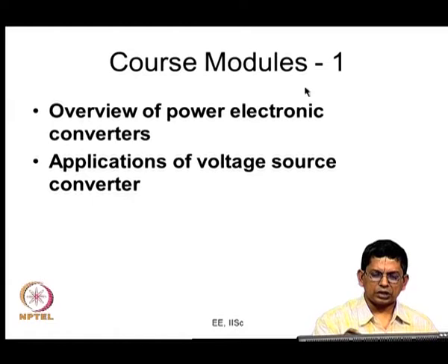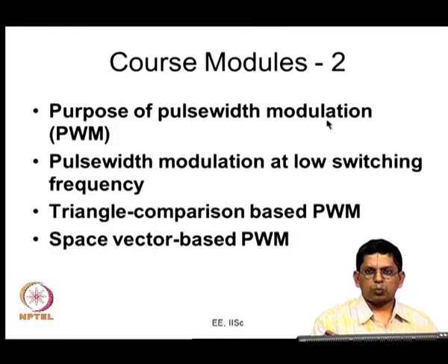So, this is for the first set of modules. These are more general power electronic course modules. Here we get particularly into PWM and some basics of PWM generation. In this we looked at Fourier series and harmonic components and symmetries, half wave symmetry, quarter wave symmetry, what happens and so on, like in these two modules for example, half wave symmetry leading to absence of even harmonics and so on and so forth.